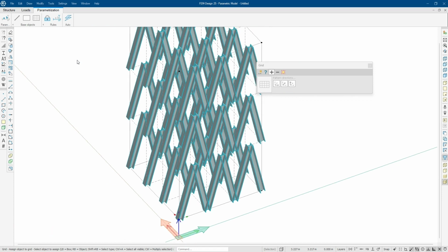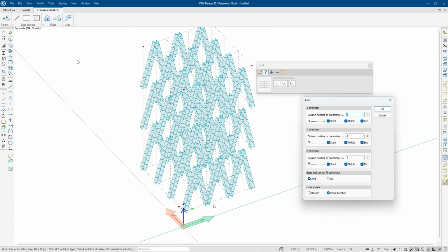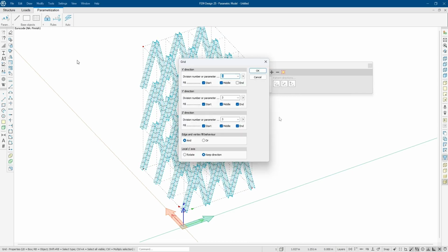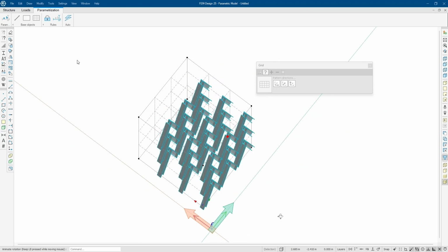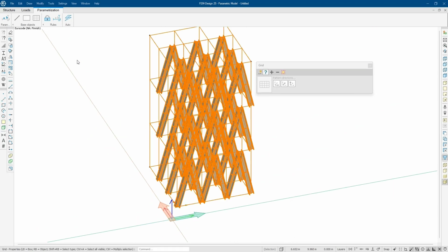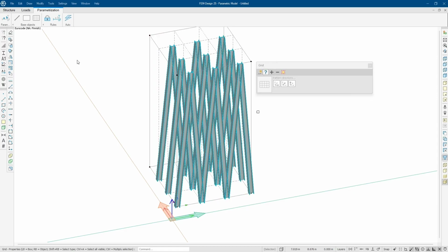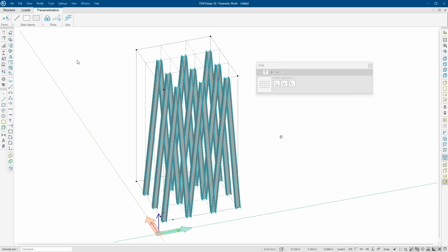And now they belong to the grid. It's important that you draw them just once, and now we can modify the division here. So we can modify the division and also set these properties. Do they fill the last cell or not? Now the last cell is not filled. You can see that only those first 3 are filled. Or 1. Now it's just 1 in height direction.